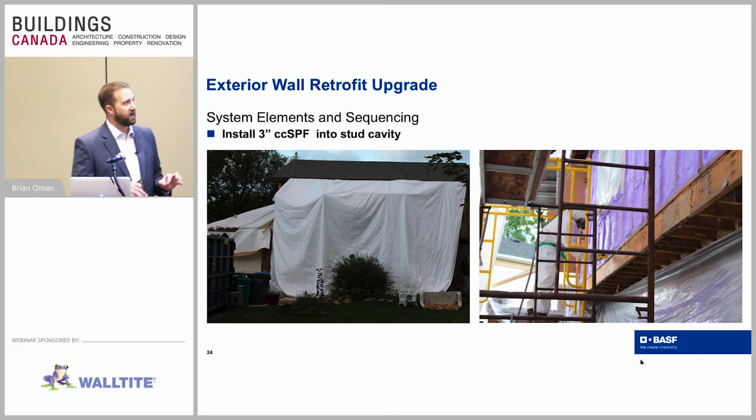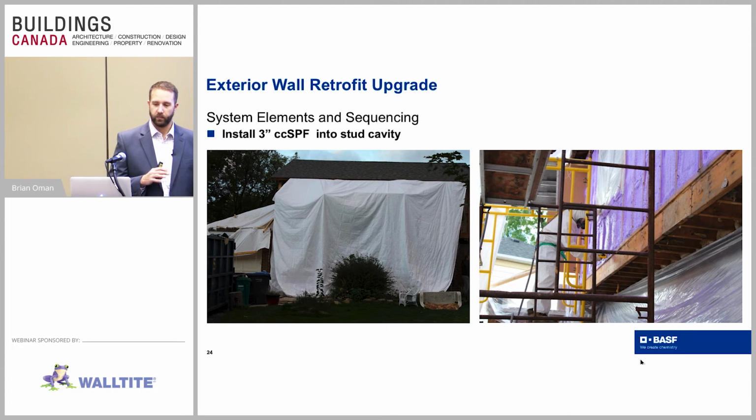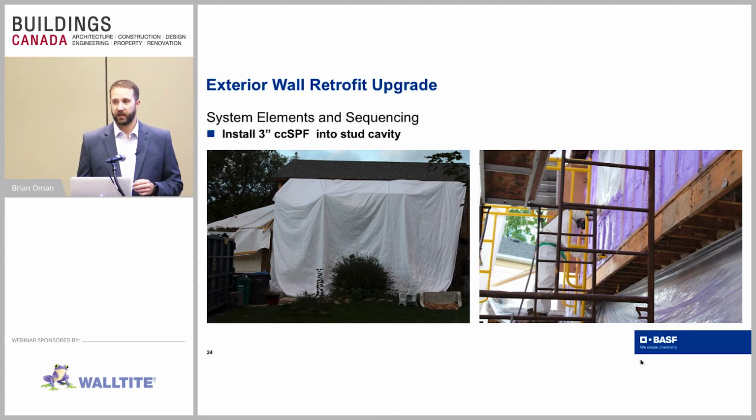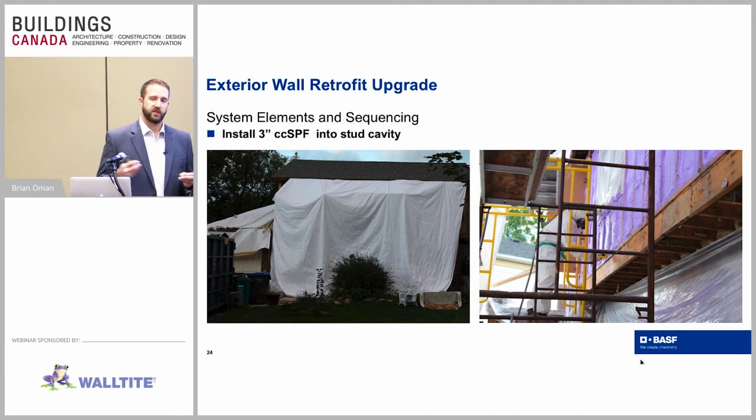So once it's opened up, once it's cleaned up and everything's been updated, we can do the application of the closed cell spray foam. So in this case, we're working in a residential environment. We're working outside. As Chris said, we're atomizing the material. We're taking two liquids, mixing them together. That's going to create a mist. Unfortunately, that mist isn't all going to go onto the surface.